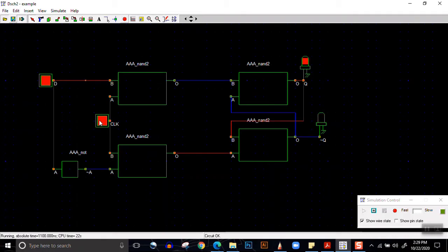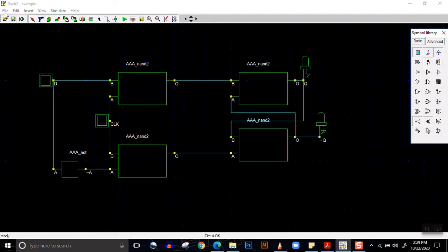So let us take a value of Q, say Q is equal to 1, that is data is equal to 1. Then again, when we switch off the clock, if we change the value of data, the earlier value of output remains. The value of output does not change. So this over here is a latch. That is, when clock is 1, the input is mapped to output. When clock is 0, the output retains its previous value. So our latch is working.